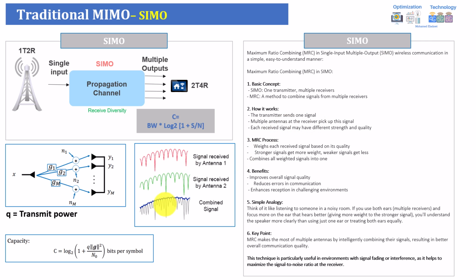And before moving to the next one, I just would like to highlight: assume you have only 4 receivers on the UE side and even on the Unit B side. Now assume what will happen in the case of massive MIMO. For example, on the Unit B side, you now have 64 receivers. So the gain will be even more maximized for a larger receive antenna array. This can be reflected in your uplink received signal or uplink performance, right?